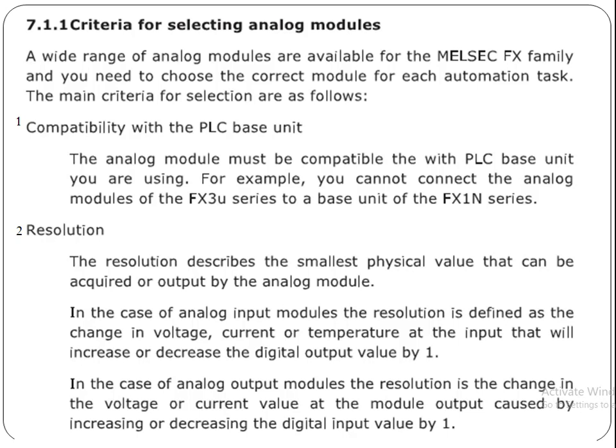Bismillahirrahmanirrahim. In this video we will discuss the criteria for selecting analog modules. There are three main criteria. First one is the compatibility with the PLC unit, second one is the resolution, and the third one is the number of inputs and outputs in the analog modules.